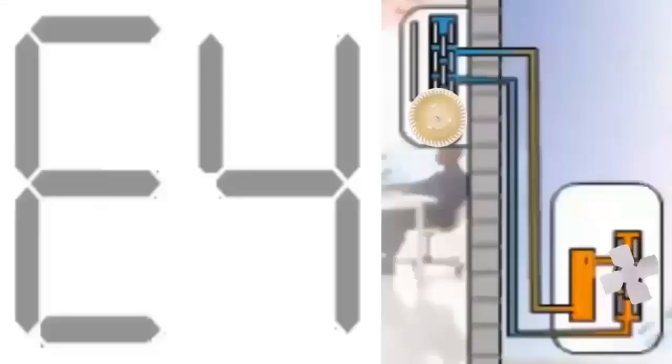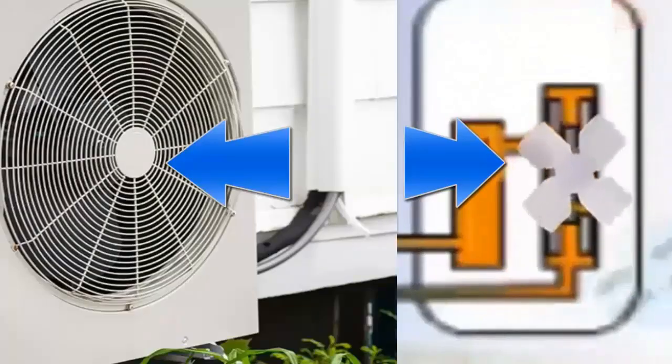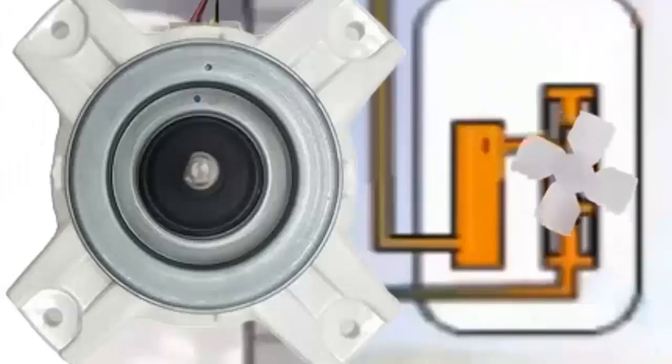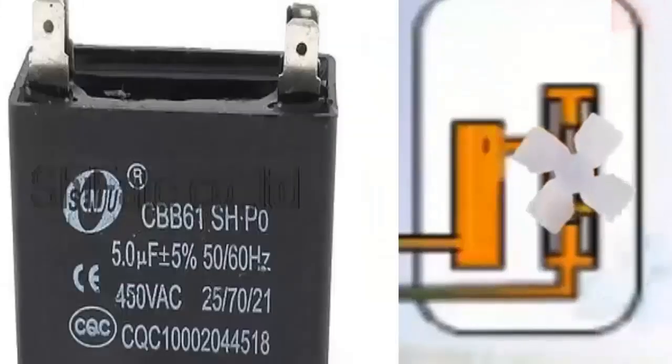Error code E7. This indicates that the outdoor unit fan speed is outside the normal parameters. Solution: A. Inspect the fan motor and its control board. B. Clean the fan, ensure there are no obstructions, and verify the free rotation of the motor shaft. C. If the fan uses a capacitor, test it with a similar one. Replace defective components as needed.